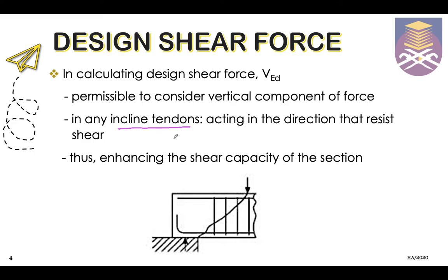Okay, so why is that? It is due to the location of the tendons itself, which will be in the direction that is opposite to the direction of cracks in our section. Thus, it will enhance the shear capacity of the section.